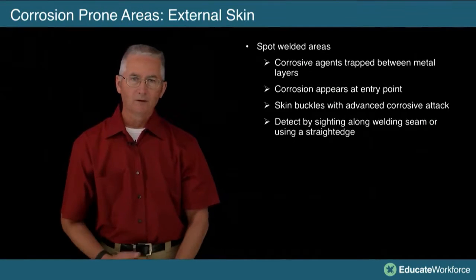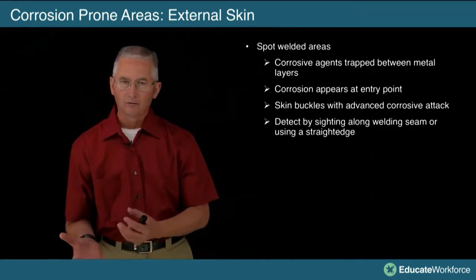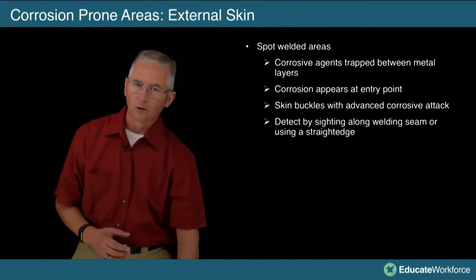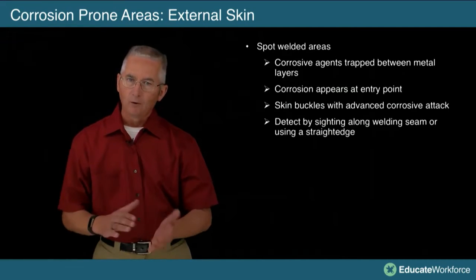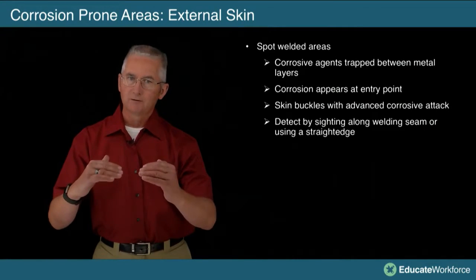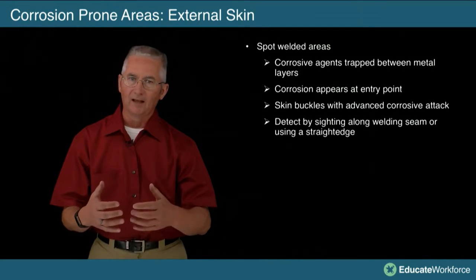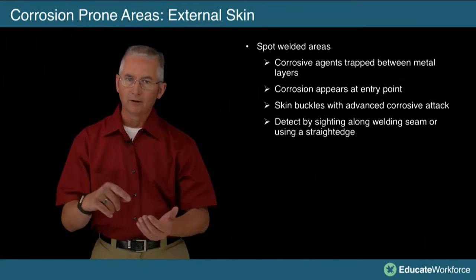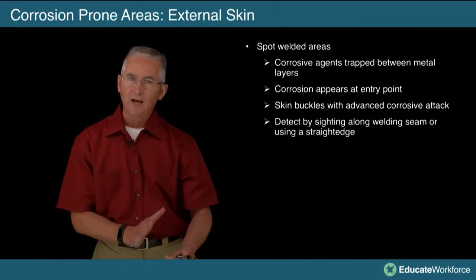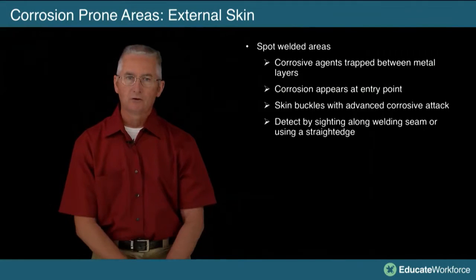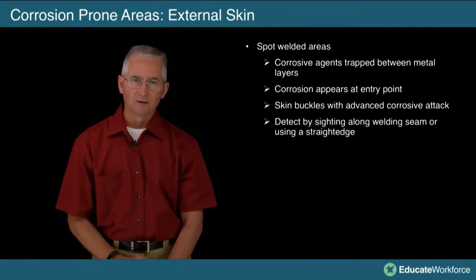Well, when we're spot welding the metal, we're increasing the temperature. That is going to cause some difference in the aluminum alloys. As we get into alloys, we'll talk about alloys, but when we heat treat these alloys, we take them to a specific temperature and rapidly cool them to get all the elements in that alloy where it's supposed to be. Well, you know what? When you spot weld it, you alter that. You add heat to it. You change that chemical mixture, which could turn to galvanic corrosion later on. So watch your spot welds really good.